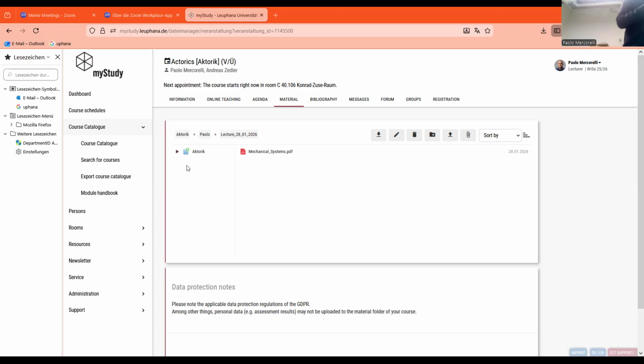A little bit easier is also this G matrix or gravitational terms, because you understand that the gravitational load acting in this position on my arm is not the same as in this position. Here it is 0, here is the maximum. This means it depends also on the angular position with respect to, let me say, the system which I consider the reference.